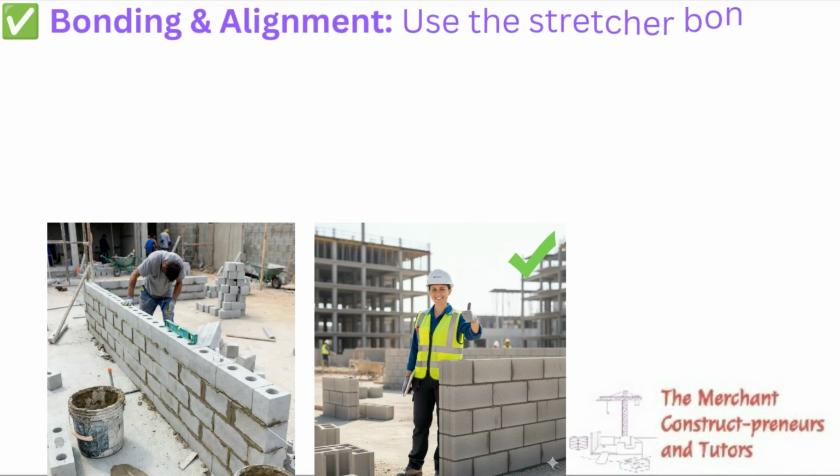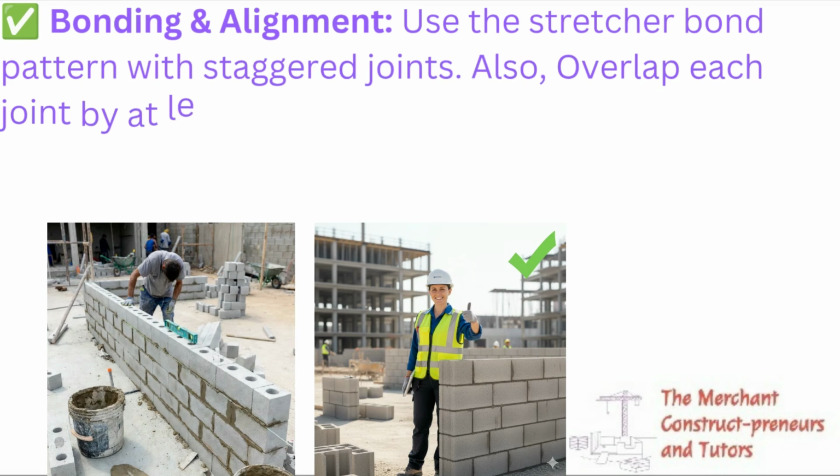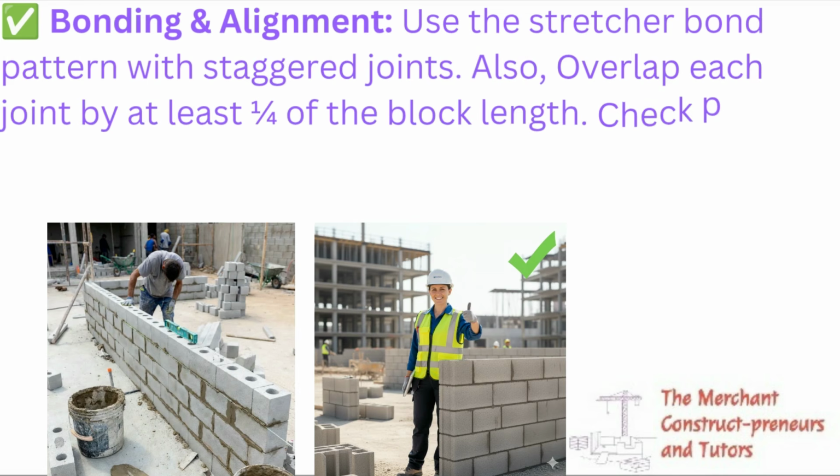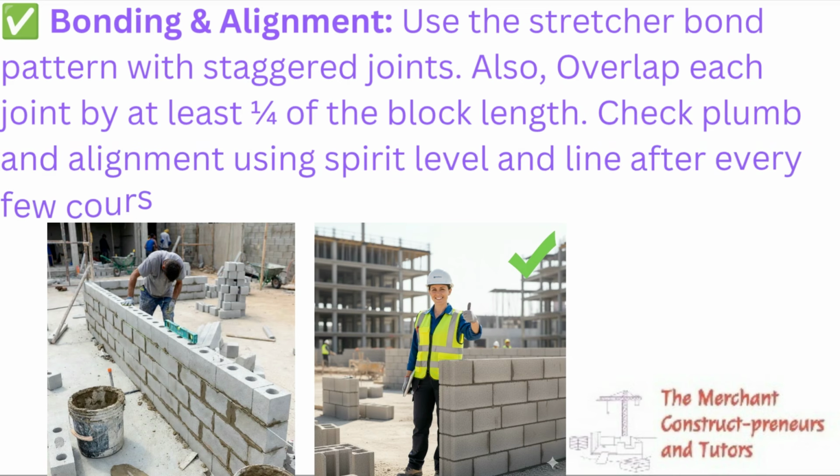You clean the surface so that there is bond between the ground, that is the slab, and the block wall before you even start doing that. If not, you just have a wall that is not bonded with the ground, and after some time it falls off.